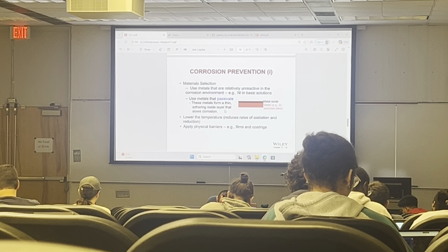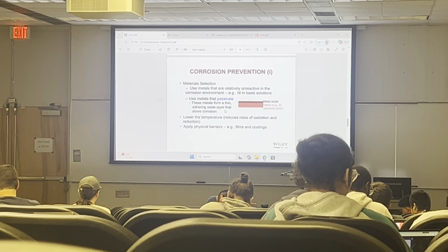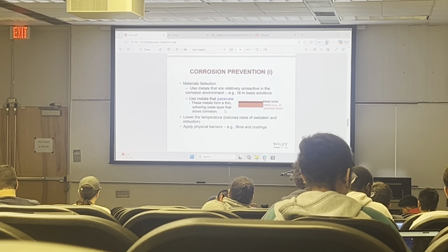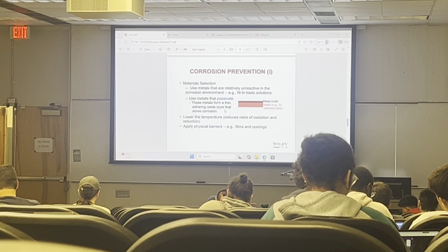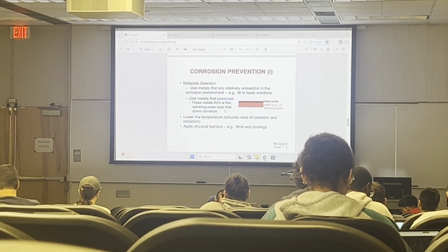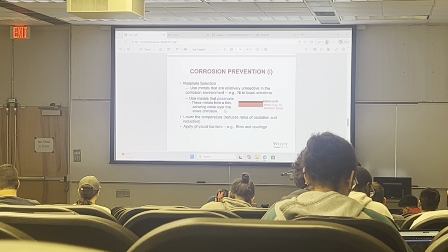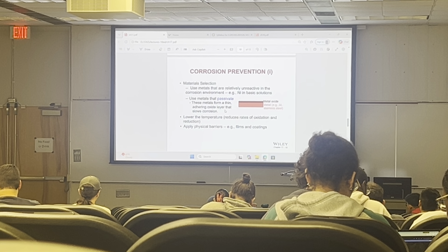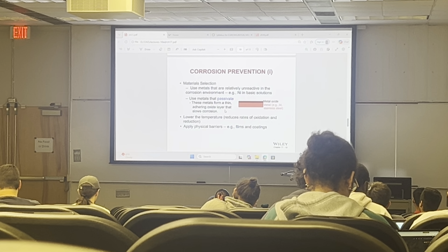Going back to the aluminum and to the performance. The reason why it's not a very smart thing to have an aluminum boat is because aluminum corrodes in the salt environment. So if you're using the boat in the fresh water, it's okay. If you're using it in salt water, it's going to corrode, and this nice native oxide that's 100 nanometers turns into white powder. How many of you have seen corroded aluminum? You know what I'm talking about?